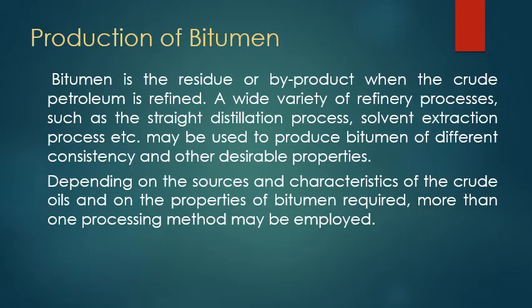At a normal range of atmospheric temperature, bitumen is in a semi-solid state and remains highly viscous and sticky. And when the paving grade bitumen is heated, it softens at a rapid rate and attains fluid consistency, and the viscosity decreases with further increase in temperature.